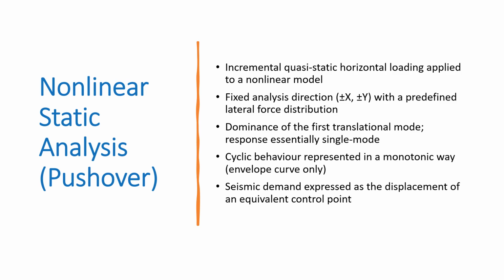It allows us to account for several aspects that can be analyzed and studied in a much more realistic way with respect to the linear methods, and also the degree of additional safety you need in the case of linear analysis, in which you are comparing forces instead of displacements.